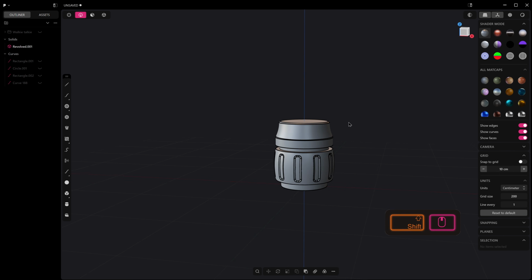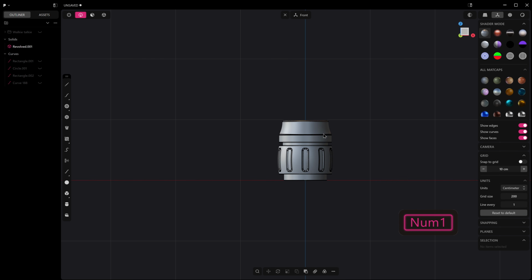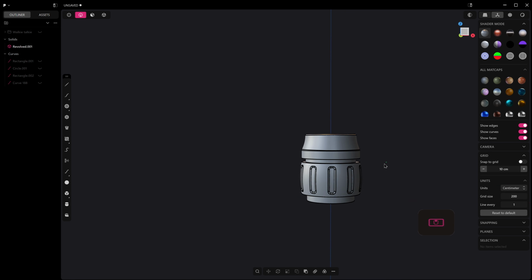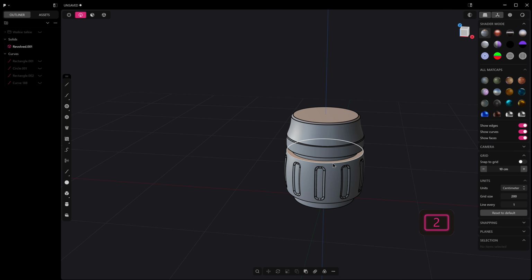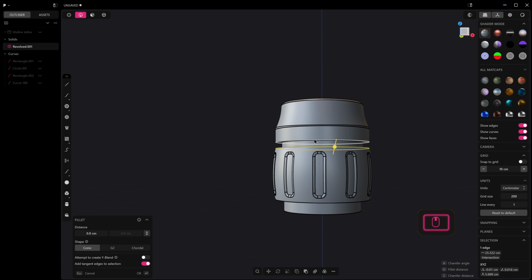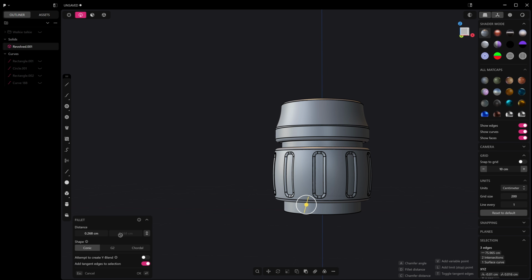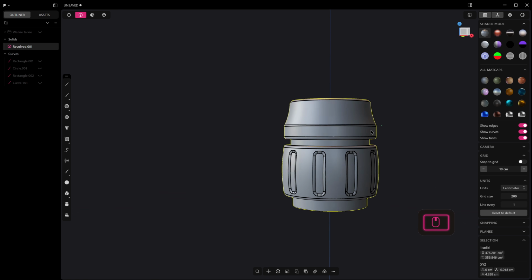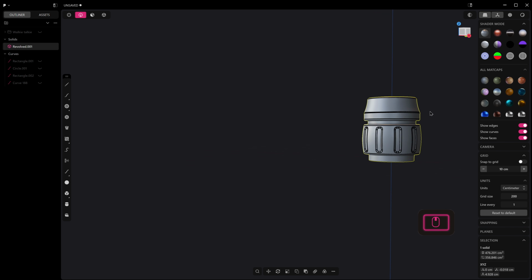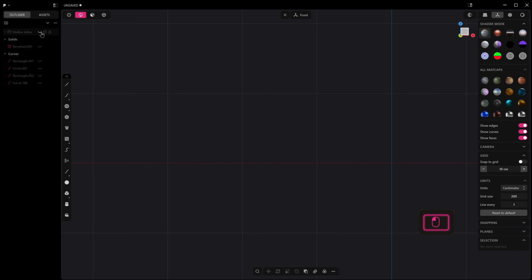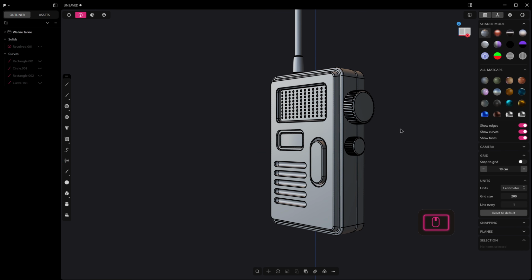So this is the base of our satellite dish, and as you can see, compared to what we did just before, this has got a lot more curvature to it and things like that. We can add fillets to all the appropriate areas. All right, giving that a nice G2 fillet. Now you can take this a lot further, but as you can see, this shape here that we've just made, compared to this shape, we've done almost two different workflows.